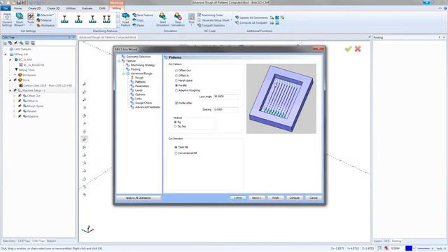So you can picture a round tool just going in and running into this wall is going to leave a whole bunch of little cusp movements, little sharp points all over. And so the profile after is going to come in, clean up any of those cusps that might be left and have it there.